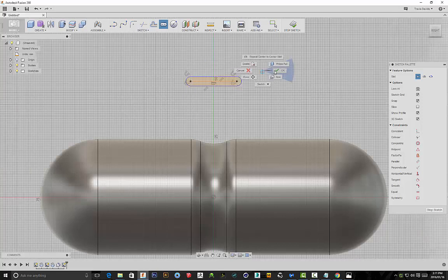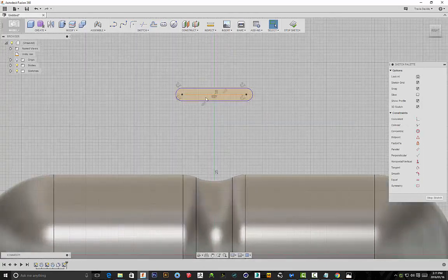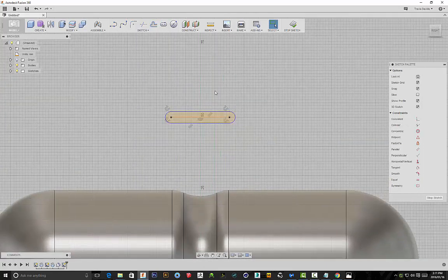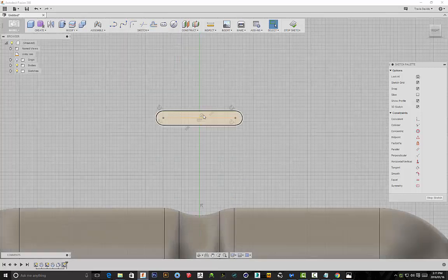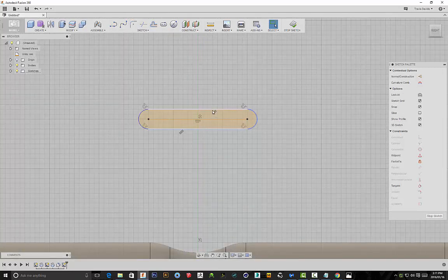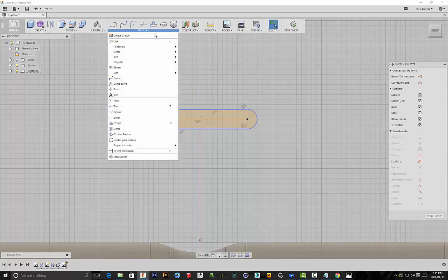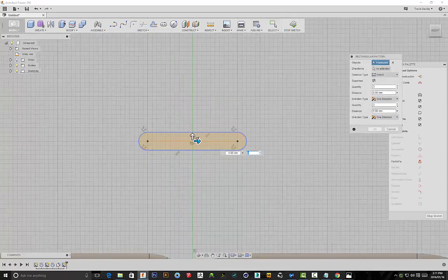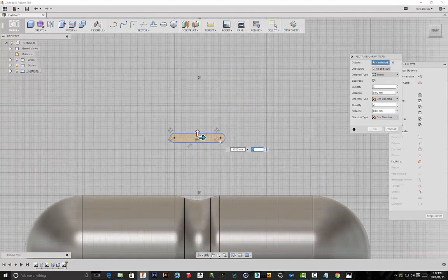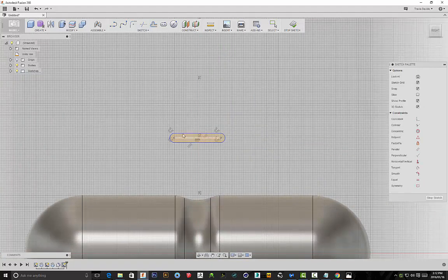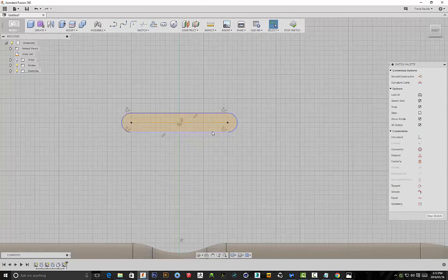4 millimeters should be fine. Okay, now here's another tip. If I actually want to duplicate this multiple times or create a pattern, we're going to be using a rectangular pattern. I'm going to select all of these edges again. I'll go to sketch, rectangular pattern, and now we've got these two arrows, which means that we can basically duplicate this way, or we can duplicate it going up.